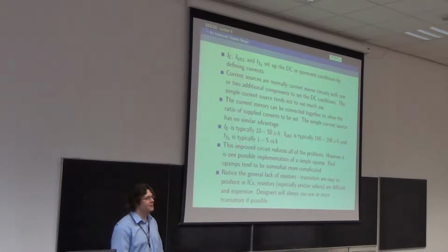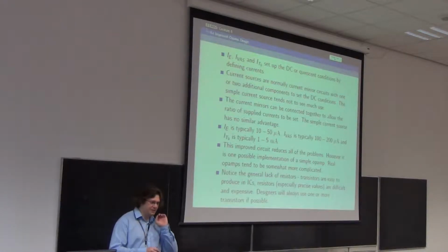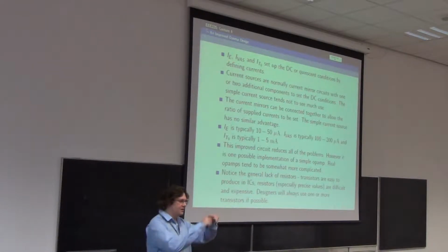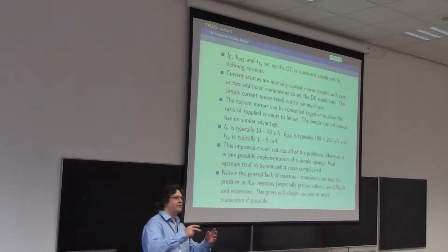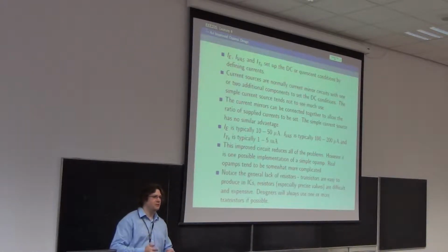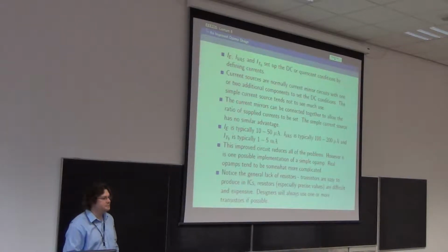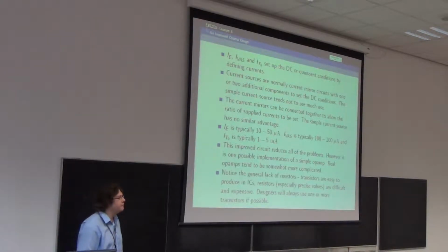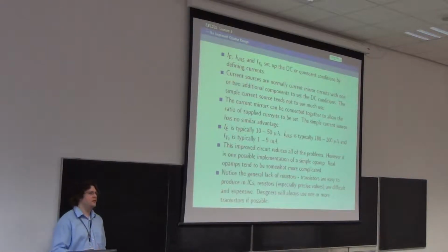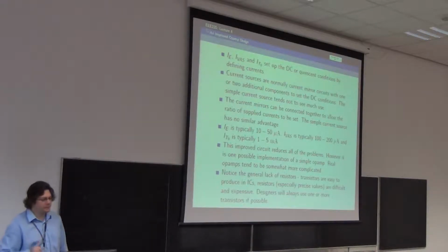Well, okay, that's a gross simplification, but just looking down in, you've got a conductor in the middle and a conductor around the outside, and they go for a long distance. So you've got a distance and an area, and a dielectric constant in the middle, so really coax looks like a capacitor at lower frequencies. If you bought an op-amp specifically meant to drive such a line, it would be able to handle that capacitance, because the people who designed the op-amp will have made it so. There is no need to worry about that.